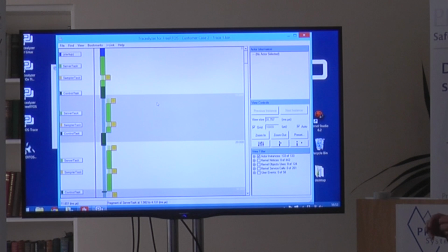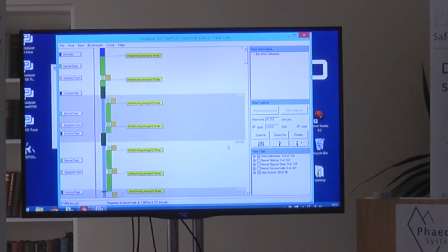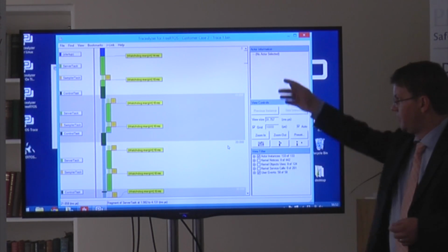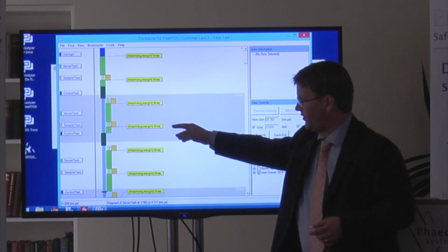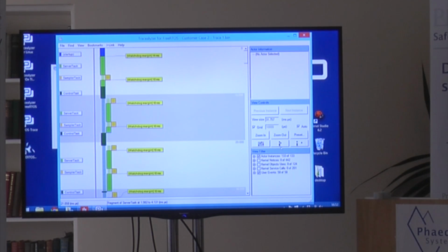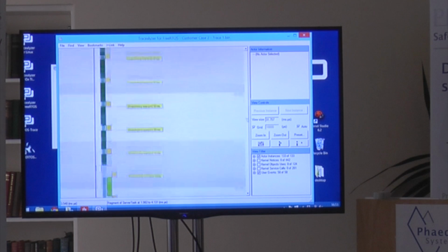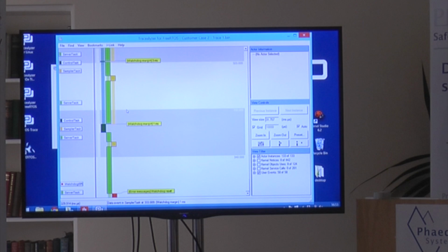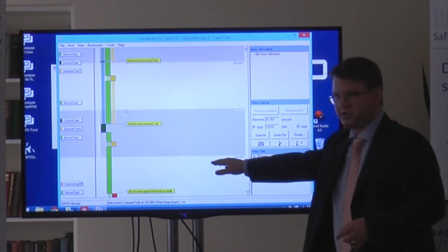In this case, they noticed that the system got random resets, and they suspected that this was due to a watchdog. But they didn't really understand why this happened. So they instrumented the watchdog events with these user events, so they could see the remaining time on the watchdog every time it was kicked. And we see here that there is a margin of 10 milliseconds every time. But then at the end of the trace, when we get this reset, we see that the margin drops. And in the end, we have this system reset as the watchdog fires.